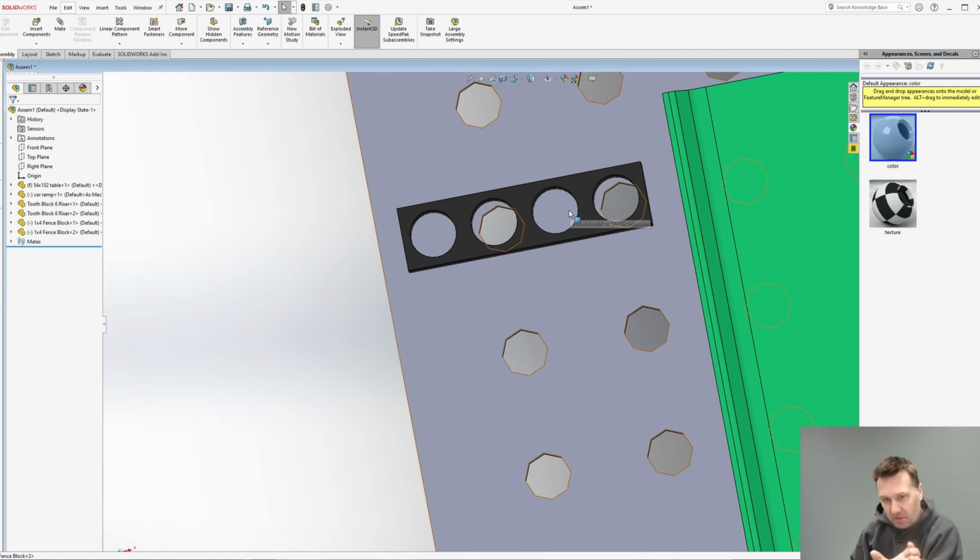Now I like to turn the blocks endo this way because the block doesn't want to rock. If you turn the block in line with the part, widthwise, there is a little bit of wiggle room in the pins, just for manufacturing purposes, and the table holes get yucky and dirty in there. The block will rock a little bit. Sometimes that doesn't even matter. I prefer to do the block like a T in line with the parts.